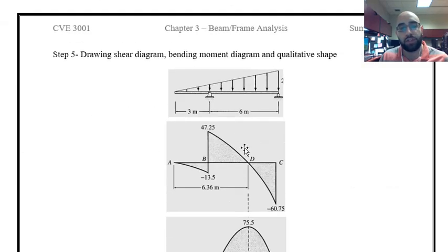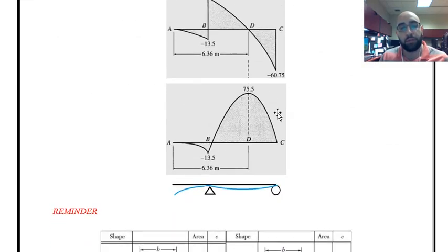And those are the equations. And the same thing for bending moment. The last step is to draw the qualitative deformed shape of the beam. And as we discussed during the presentation, whenever we have a positive moment, I have to plot a curve with positive concavity or concavity in the upward direction, like a ball in the upward direction, like this.